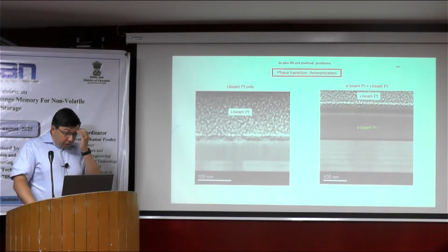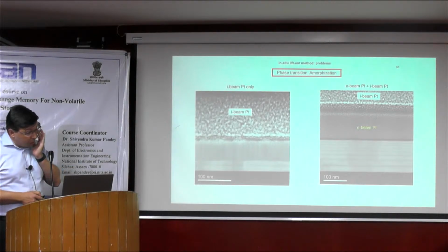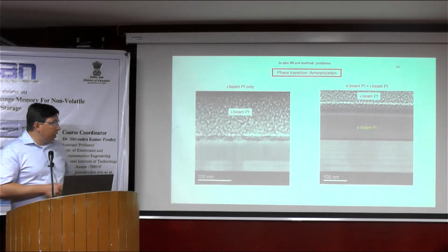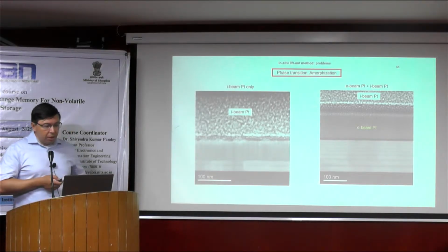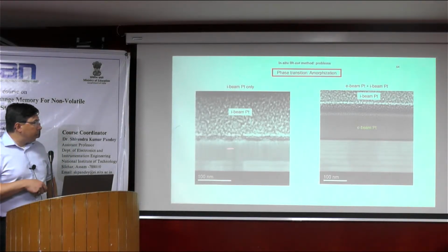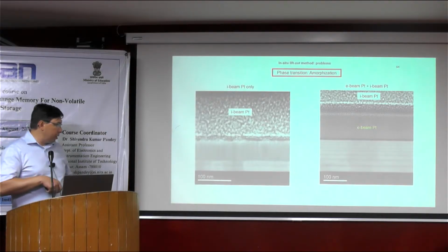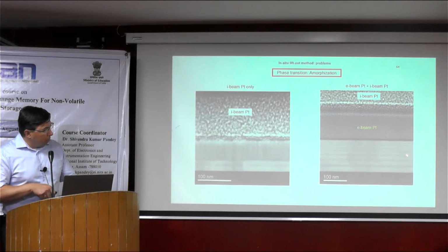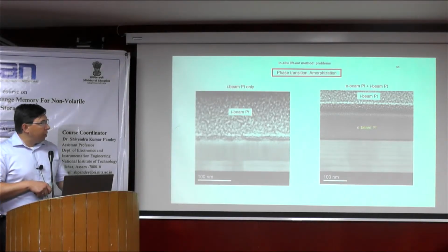And another problem. This is the procedure and preparation by FIB of the lamella itself, of beam sensitive materials like phase change materials, chalcogenide phase change materials. Here we have a structured thin film. This is a multilayer of germanium telluride and antimony telluride.